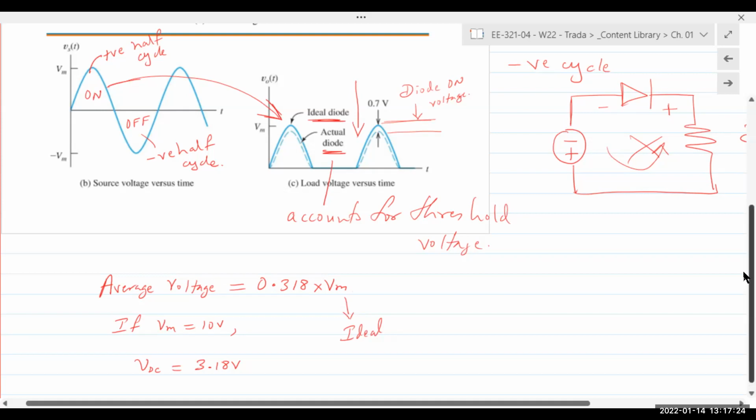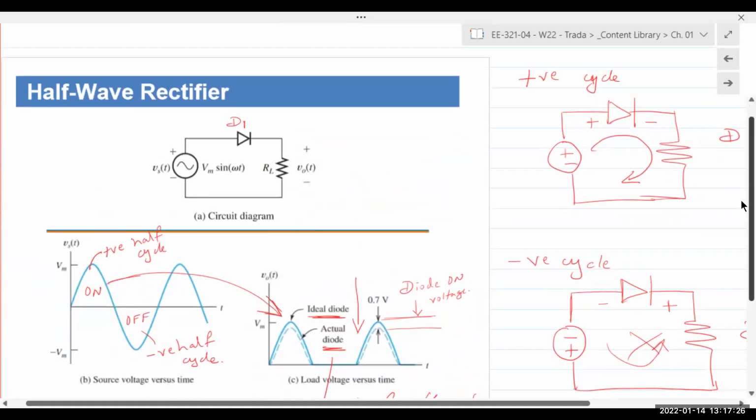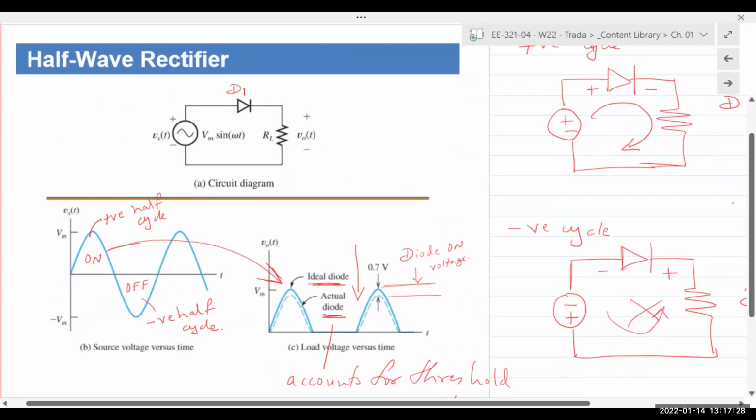Half-wave rectifiers, as I said early on, were used in really cheap adapters. So here I brought a few things for show and tell. These are known as wall warts. Even the smartphone chargers that we get nowadays are wall warts. This is simply a transformer. Typically we used to have adapters that would have a transformer, diodes, capacitors and resistors all inside one box. But this is specifically a transformer.